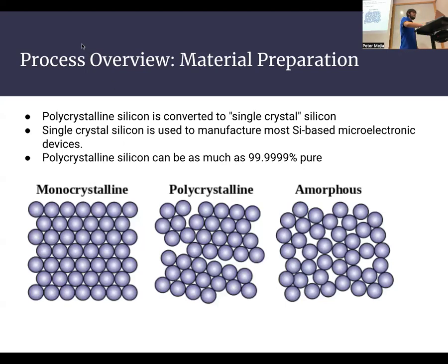Also, before you go. Yes. When you put a dopant into silicon, it takes a certain amount of energy for the electron to actually leave the atom that it forms a bond with. The work function, right? Yeah, so for any element one left or right over, that is about 40 milli electron volts, which is room temperature. If you go sulfur, it's about 300, and the second electron is 600 milli electron volts. So at room temperature, it doesn't help for conduction at all. Okay, cool. Thank you for that.